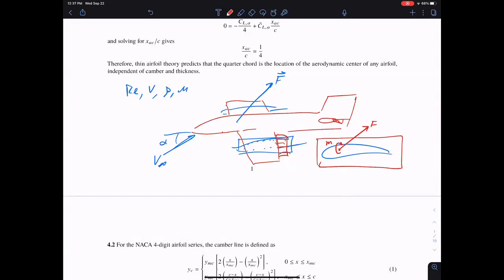So now the force and the pitching moment actually is just an integral of all of the pressure, right? If we looked around this whole airfoil and we knew what the pressure was at every point, and not only pressure, if we zoom in on the surface of that airfoil, we've got pressure that's acting normal to the surface. Then we also have some shear happening tangential to the surface. Well, it turns out that shear, we call this tau at the wall, is equal to mu du dy. We really haven't talked about this much, but what I wanted to show is that it depends on the viscosity. Well, at a first cut here, we're going to neglect viscosity. For potential flow, we're neglecting the effects of viscosity, at least in this sense. And so we're only going to look at the pressure forces, okay?